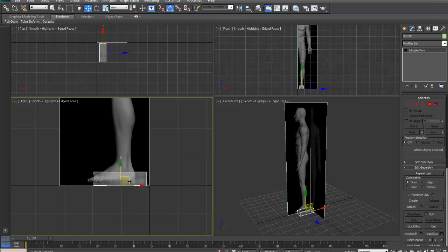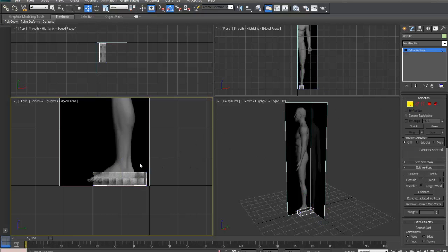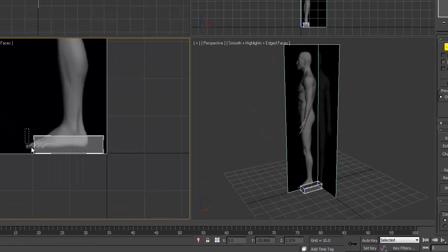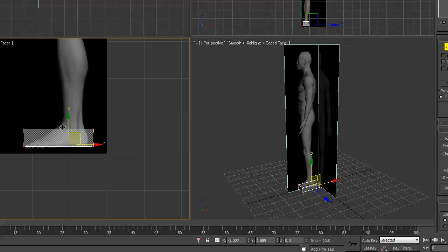So, alright, what we've got to do is resize this box. So if I come in here, I'm going to the vertex sub-selection, and we're going to just grab the whole thing and just move it up to where it should be, which is about there. We'll grab these two back guys and we'll push them through to about there. These two up here, and push through to there, something like that. I want something to be a little bit like that. You can see what I'm doing there.